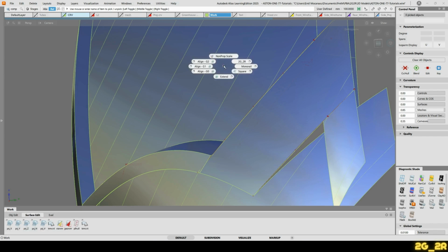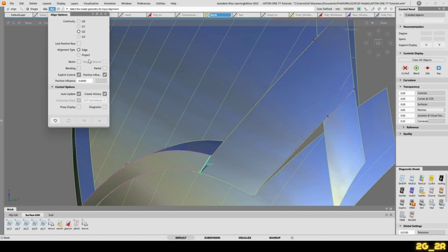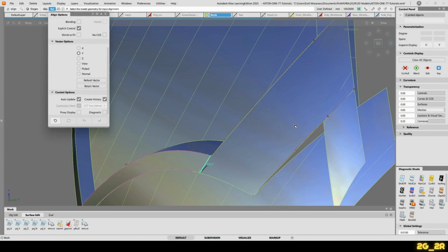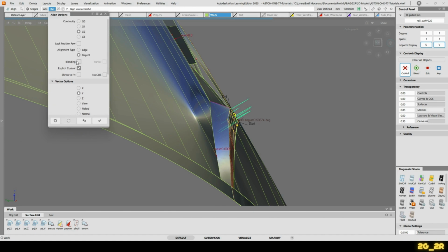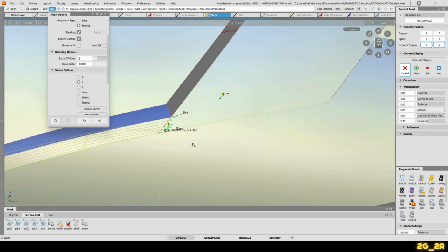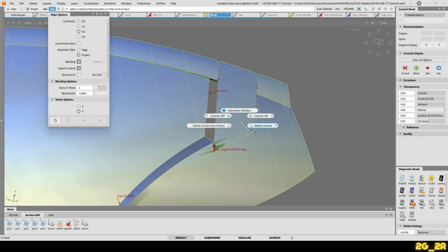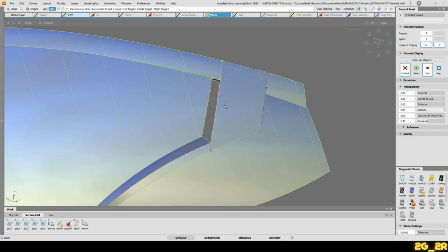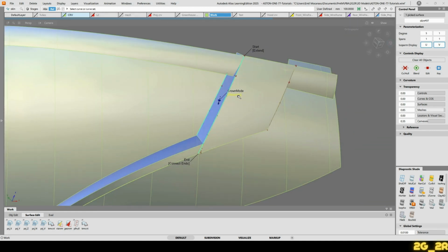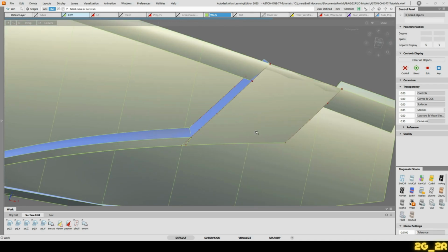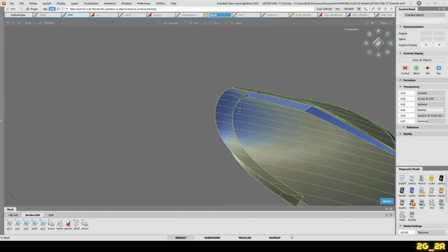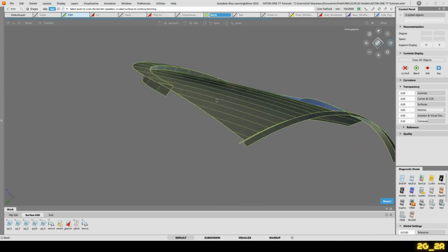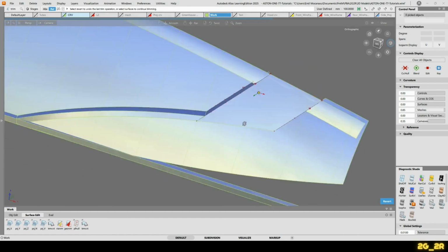And now what I'll do, I'll align this surface, projecting it in a side view onto this surface here. And I'll hit blending in here, 2 CV rows, so it finally adjusts it to that. Hit a skin in there. Trim this back. So we've got all that in there.